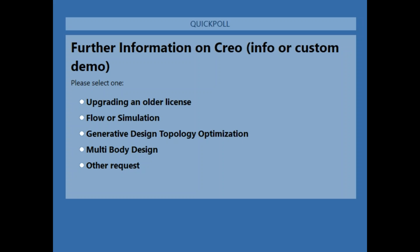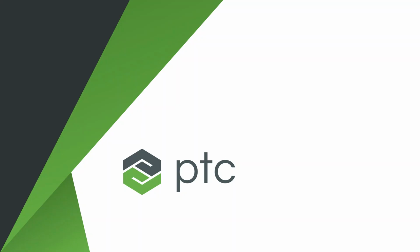Next question, I sent this to you, Bill, so I hope you can see it. Does running multiple load cases get you a different geometry for each case, or one geometry that works for all of them? If you're running them separately, you'll get different geometry. If you combine all the loads together, you'll get a single geometry. The trick there is how to do the weighting, because one load case could be more important than another. And there's no special tool for that. You just go in and adjust the loads. And if you have a load that's less important, you just give it a lower value. It's extremely simple.